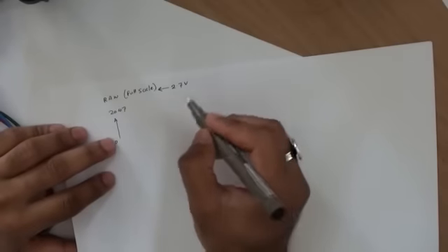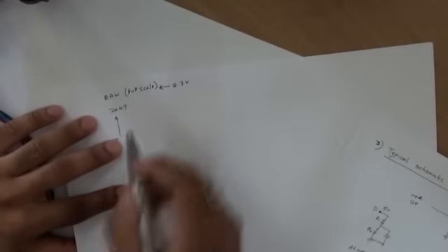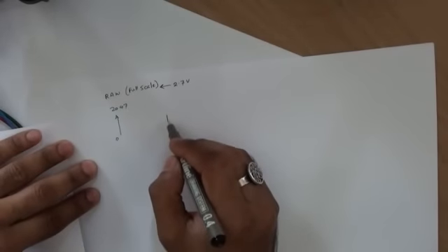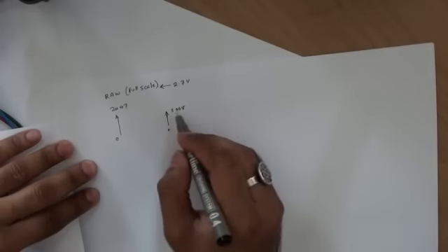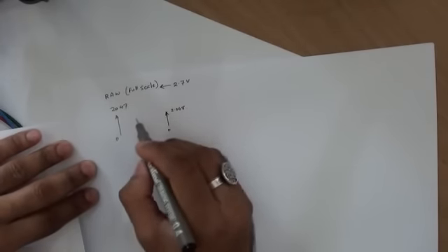So if you have your voltage reference at 2.048, which is the real analog value, you would be expecting a raw value less than that to represent 2.048. So your actual 2.048 would be somewhere up here, and that will give you a raw value reading less than 2047.